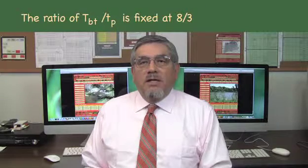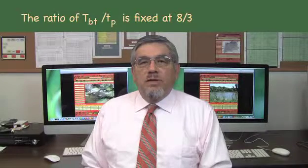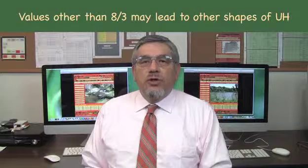The NRCS method provides a unit hydrograph shape and therefore leads to more reproducible results than the Snyder method. However, the ratio of triangular time base to time to peak is fixed at 8/3. This renders the method inflexible in certain cases. In particular, values of triangular time base to time to peak other than 8/3 may lead to other shapes of unit hydrographs.